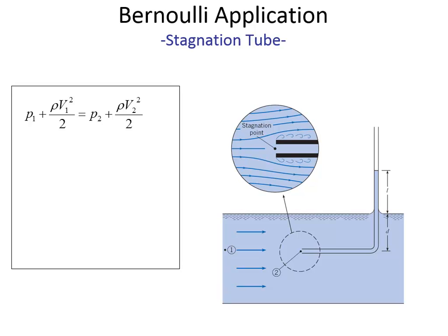And you can prove that to yourself by taking a straw to a water park, where the jets come out as you're about to go down the water slide. Just put the straw in there and the water would go squirting all over the place. But if the velocity is a little bit lower, the water won't blow all the way out of the straw. It'll just rise to a certain level and then it'll stop. And how high above the liquid level it rises can be used as an indication of how fast the velocity is. It's like a velocity meter. How high the water level rises, it's going to go higher and higher with a big velocity, and then it will come down with a lower velocity.